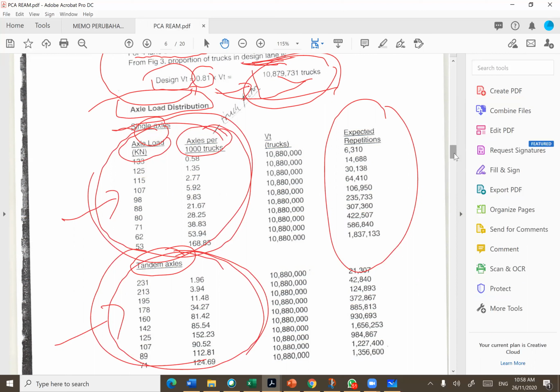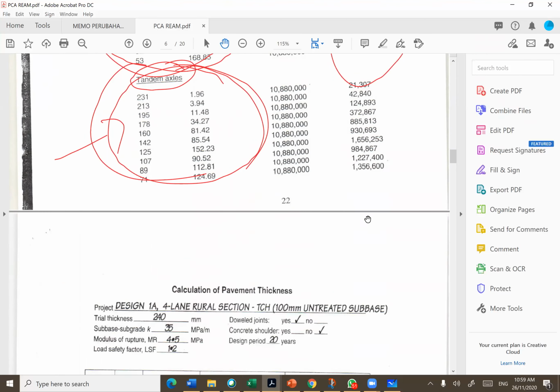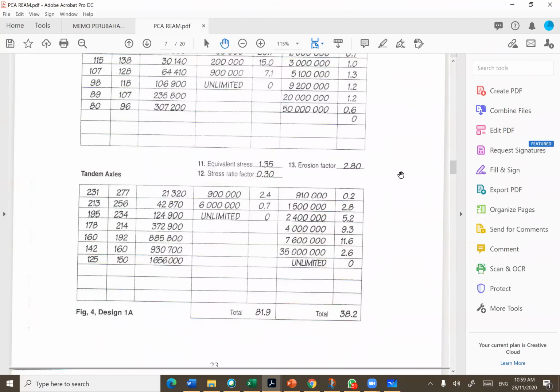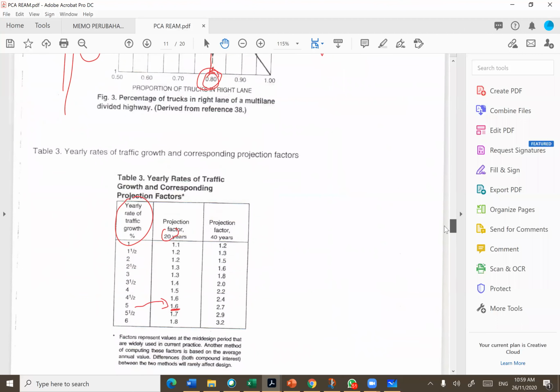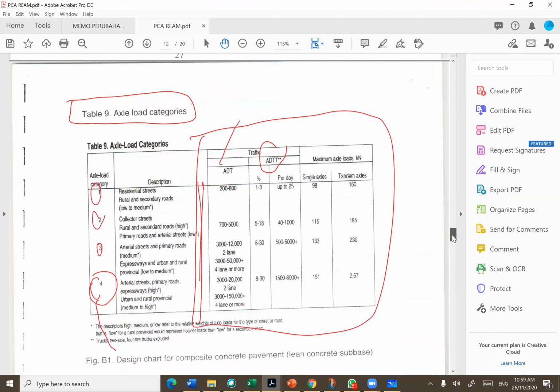What do you do if it is 4 lanes and more? Because the graph is for 2 lanes and 3 lanes, the graph of the percentage of trucks, the one to get 0.81 earlier. Normally, if it is 4 lanes or more, I think they will need to conduct a traffic study, traffic counting, but it is quite difficult.